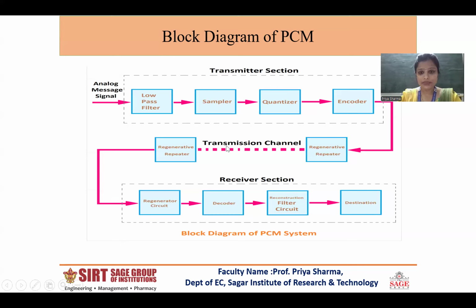In the pulse code modulation receiver, the serial to parallel converter converts the serial pulses received from the transmission line to parallel pulse code modulation codes. The digital to analog converter, or the decoder, generates a sequence of quantized multi-level sampled pulses, resulting in reconstituted pulse amplitude modulated signals.